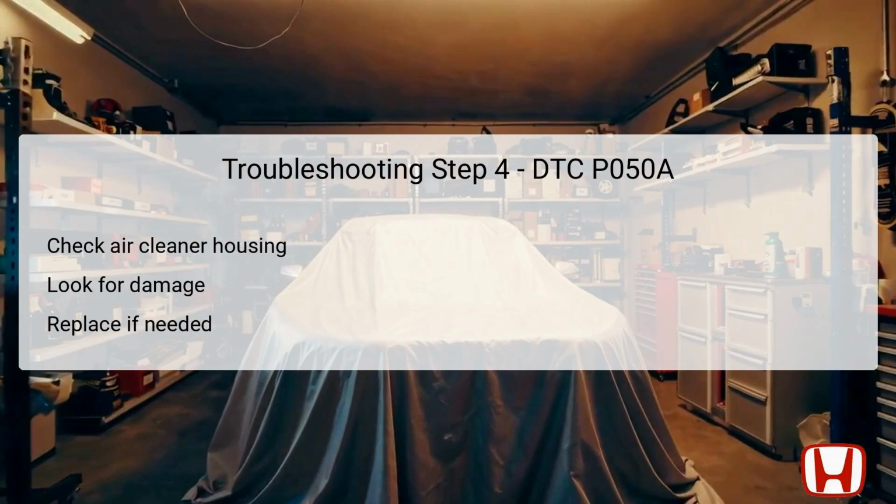In this step, examine the air cleaner housing closely for any signs of damage. A compromised air cleaner housing might allow unfiltered air to mix with the intake air, potentially introducing contaminants that can harm engine performance. It's crucial to ensure that the housing is structurally sound and permits the proper operation of the air intake system. If any damage is detected, replacing the air cleaner housing becomes necessary to maintain the integrity of the engine's air supply. If the air cleaner housing is in good condition, you will proceed to the next troubleshooting step for a thorough assessment.